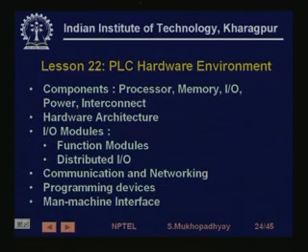In the last lesson we talked about the PLC hardware environment, the kinds of processors, the typical specifications of processor, memory, IO, the buses, bus extension, various kinds of special purpose IO modules like function modules, distributed IO modules, various kinds of communication and networking modules like industrial Ethernet. Then the devices that are used for programming PLCs, developing programs and then downloading, and finally man machine interfaces which can be connected with PLCs. So, this completes our logic control module.